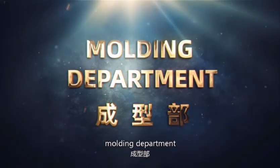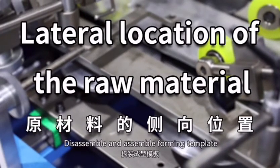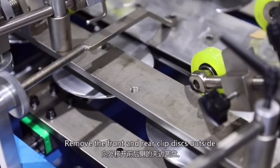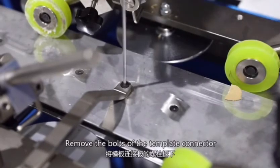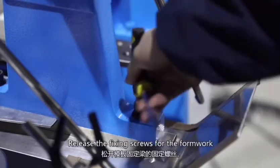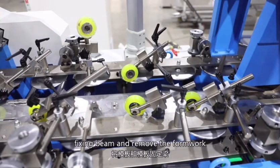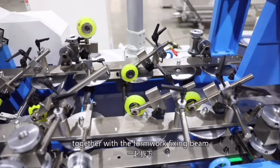Molding department. Disassemble and assemble forming template. Remove the front and rear clip discs outside. Remove the bolts of the template connector and remove the template connector. Release the fixing screw for the formwork fixing beam and remove the formwork together with the formwork fixing beam.